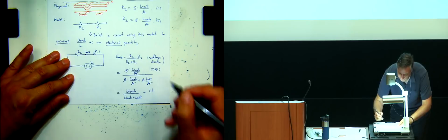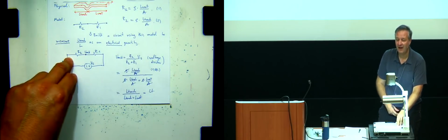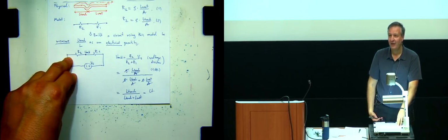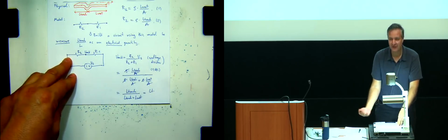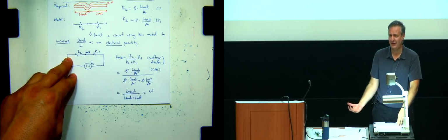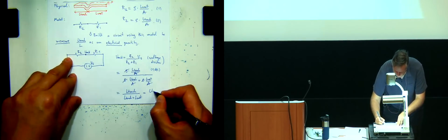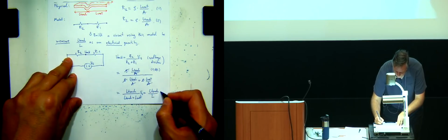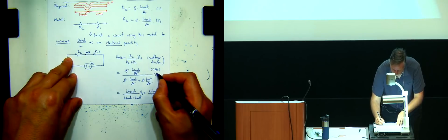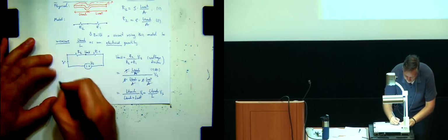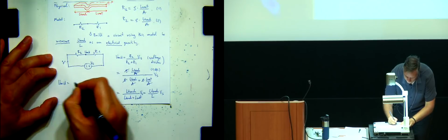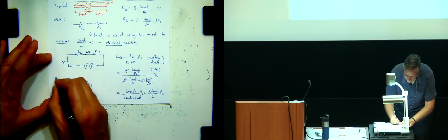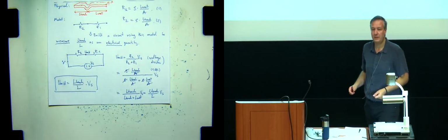Oh, I forgot something. What did I forget? How do I find out whether I forgot that or not? Units, right? So I saw that this is unitless. I'm like, hey, this doesn't make sense. This should be voltage, right? Over L, so times Vs. So let's repeat it here. U mid equals L touch over L times Vs. That is actually what I wanted, right?